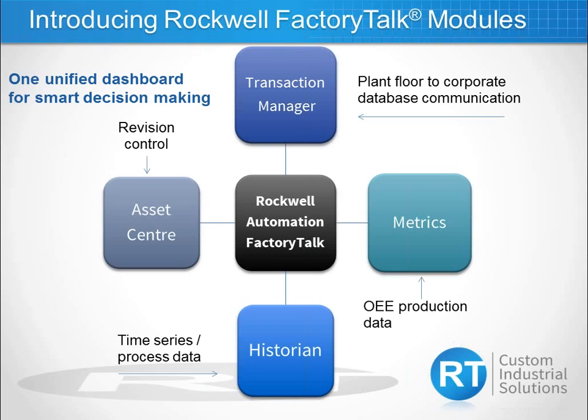And being out in the trenches, a lot of times I used to work with SQL all the time, and as I said before, the SQL Server is great when it's small, but as it grows and grows and grows, sometimes years, and the data is not purged or corrected or whatever, you could literally go for lunch, come back, and the data is still loading. With the Historian, the OSI Pi data engine in there, I've literally seen a couple of years' worth of data brought up in like 6 to 8 seconds. It's amazing the difference in the efficiency and the strength of the Historian server itself.